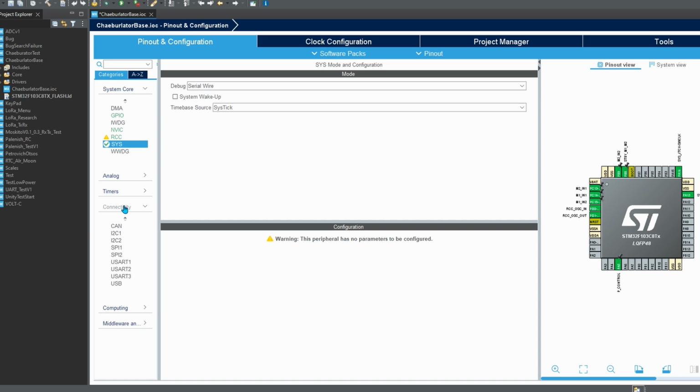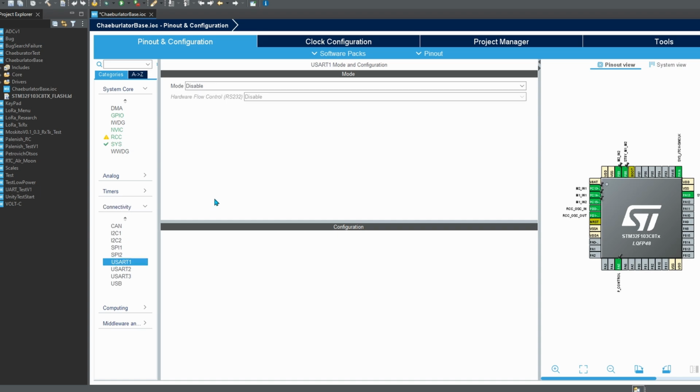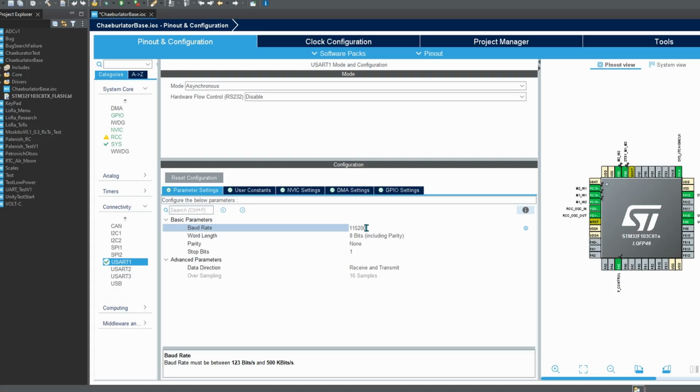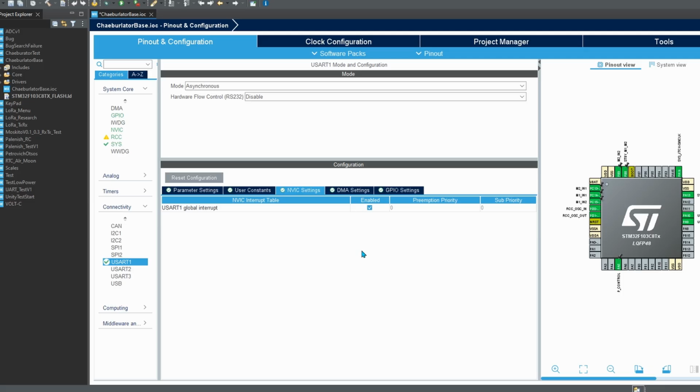Now let's add the UART settings. We will use it to receive and transmit data from and to the terminal. When receiving symbols, we will trigger an interrupt, placing the data in a queue. We will discuss the queue later. Sending will be in blocking mode, but since we are using an operating system, blocking mode won't be noticeable.